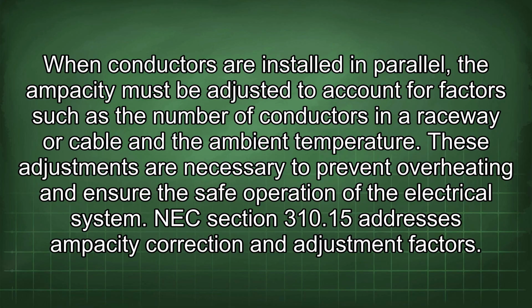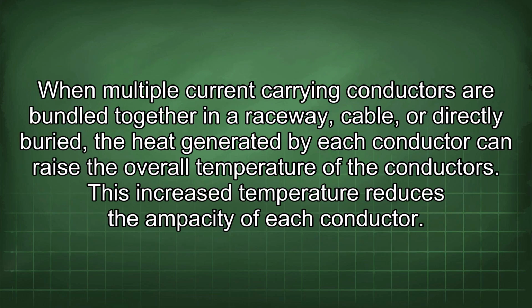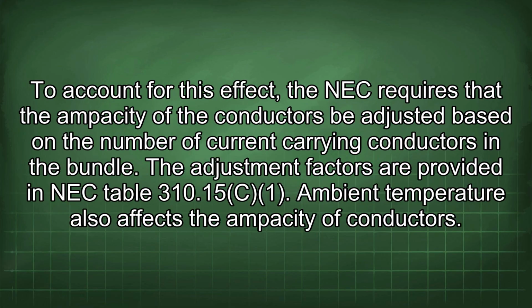NEC Section 310.15 addresses ampacity correction and adjustment factors. When multiple current-carrying conductors are bundled together in a raceway, cable, or directly buried, the heat generated by each conductor can raise the overall temperature of the conductors. This increased temperature reduces the ampacity of each conductor. To account for this effect, the NEC requires that the ampacity of the conductors be adjusted based on the number of current-carrying conductors in the bundle. The adjustment factors are provided in NEC Table 310.15.